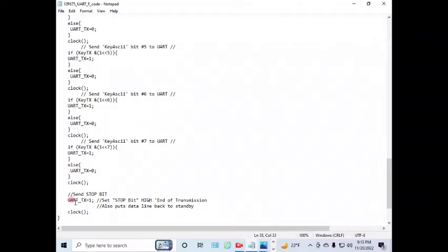And that's when we make the UART TX line high, because the receiver reads a high to end the transmission. Okay, so when it reads that high, it knows that that's it. There's no more data to be sent. It goes back in idle mode. It sets the line high. So it also sets the data line, what we said before, in standby.